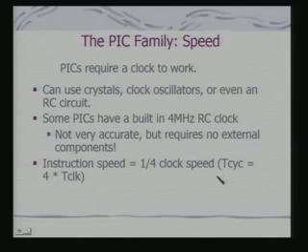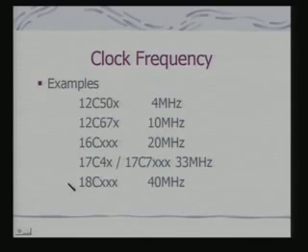So I talk about the instruction cycle, which is 4 times the TCLK. These are the typical parameters that we refer to in a PIC architecture. So where does this factor 4 come from? Let us try to understand that.